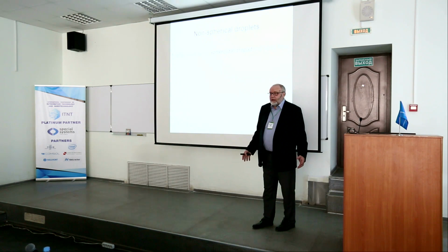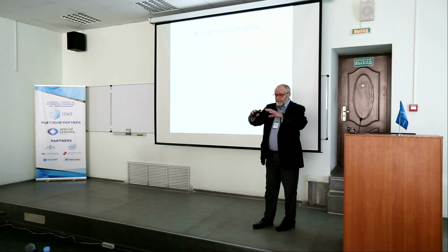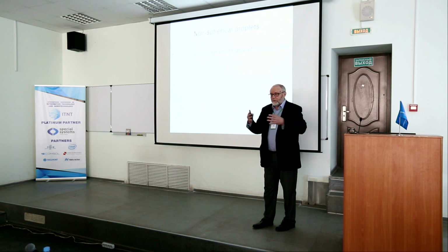The general modeling of non-spherical droplets is not really a very challenging task, because many people have worked on it using various approaches to modeling the evolution of the droplet surface. For example, the level set approach or the volume of fluid approach. These are some of the most popular approaches to this sort of problem. But at the same time, we can apply them to modeling one or two droplets. In all our applications, we are dealing with millions of droplets. To apply, for example, the volume of fluid approach to millions of droplets is a hopeless task. It is a non-starter.